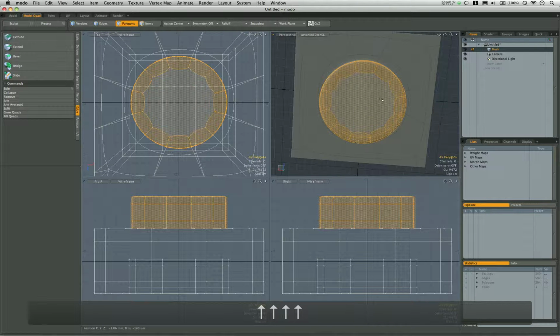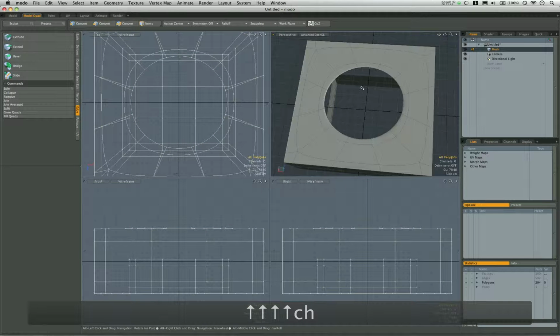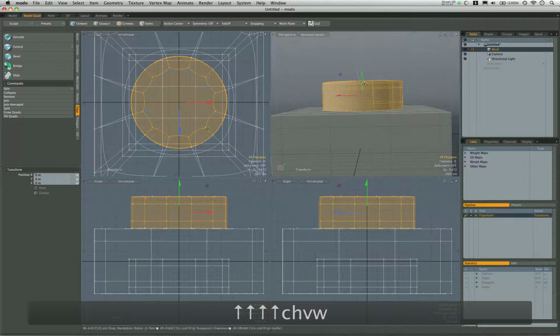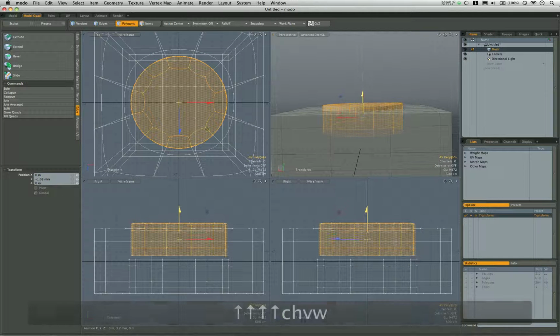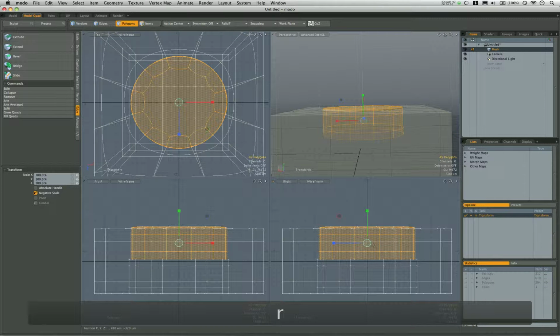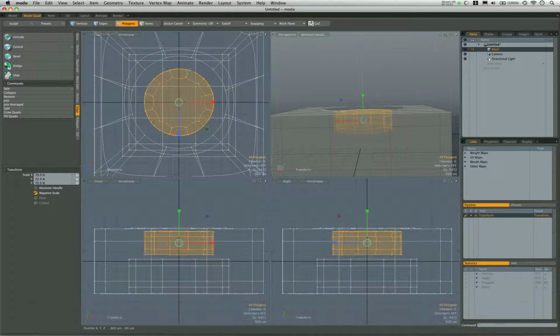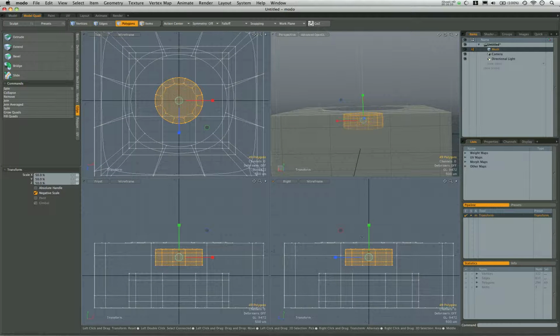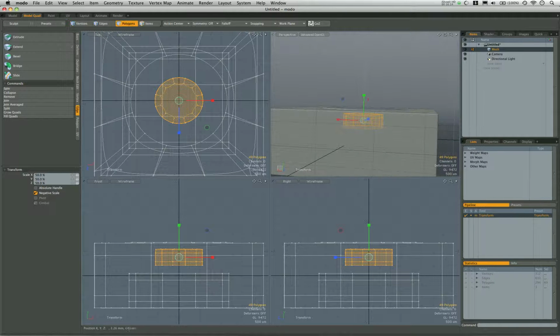So what I'm going to do is copy and then hide this geometry and then paste. And now I'll be able to double click on that piece and move it down. I'm just going to move it pretty much down until it meets 1.5 millimeters, where it will actually meet exactly. Then I'm going to scale the whole thing down to 50%, because instead of 4.8, we want 2.4 millimeters as the height on this.